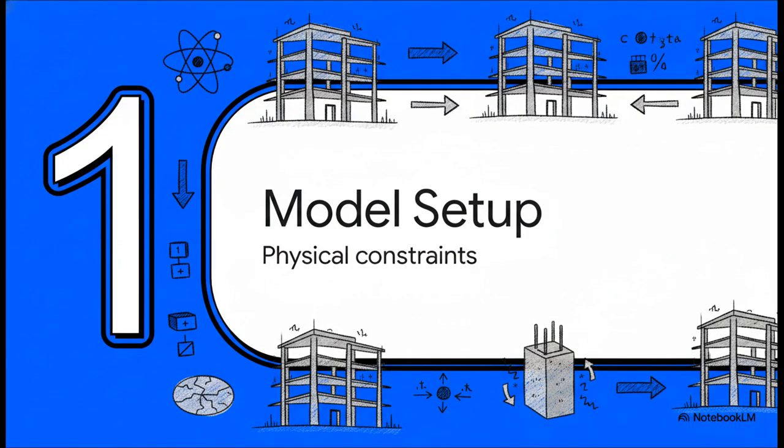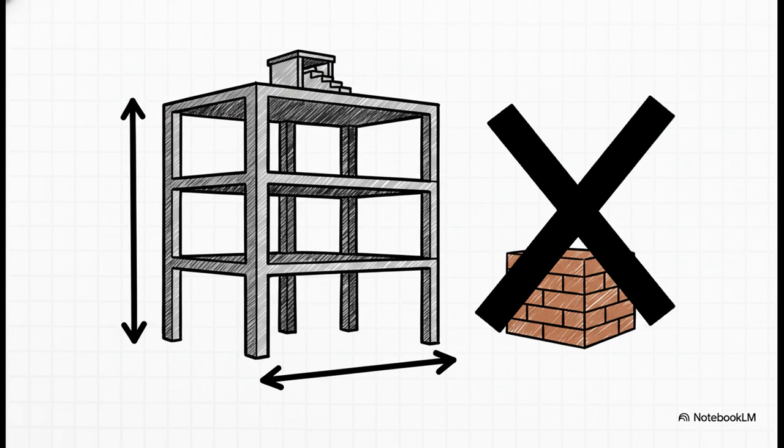Okay, kicking things off with Section 1, Model and Material Setup. We're working with a pretty standard digital twin today. It's an ordinary 3-story residential building with a stair cover, a plinth area just under 92.95 square meters, and a 3.2-meter story height. Now, crucially, we are relying entirely on the reinforced concrete frame to resist all the stress. We're assuming zero structural contribution from the masonry infill walls. You know how it is. It's a conservative, incredibly safe engineering approach.